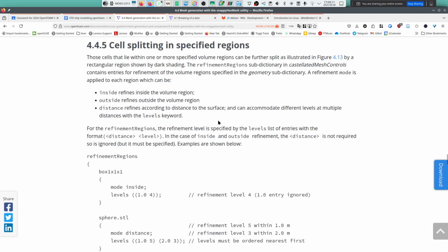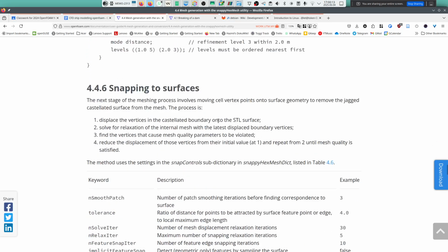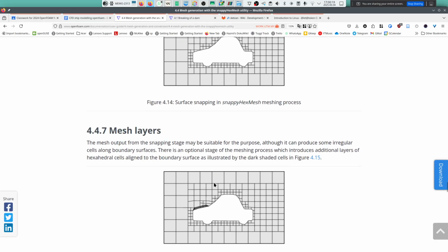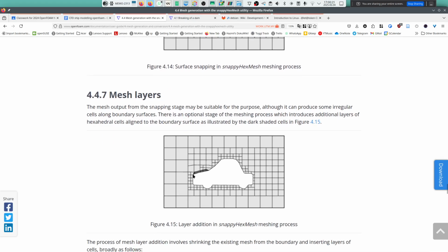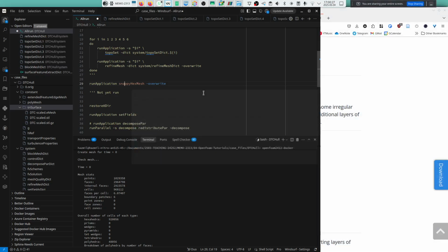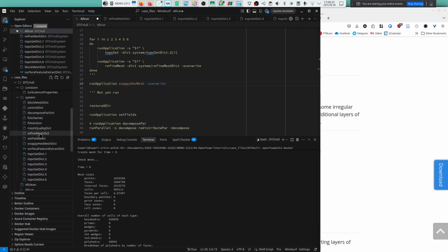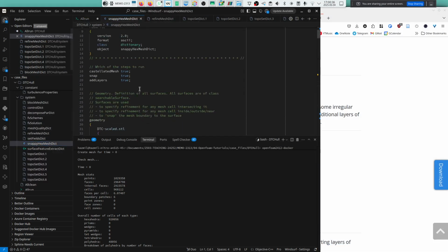So the nodes will be moved so that they are attached exactly on the body. And the next step, you will create the boundary layer mesh. All of these steps can be found inside the snappyHexMeshDict utility. So we double click on this.